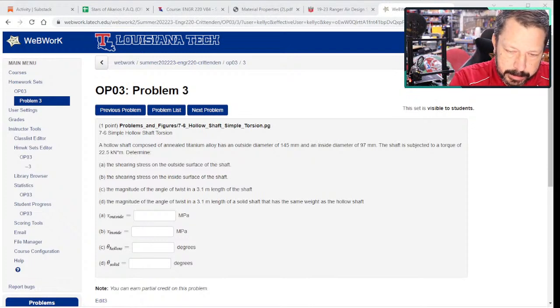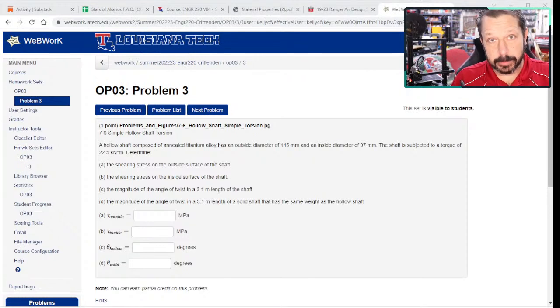We have some dimensions about the diameters and the length. So we'll just do the diameters this way. There's the outer diameter. Normally you show diameters on a circular view, like if I had drawn the end view and had circles, the diameters would be labeled on that instead of the side view, but I'm not going to draw the circular piece, I think.